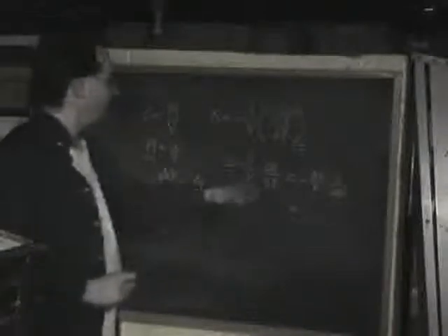So here we can write this as negative delta V over V times 1 over delta P, the pressure. We can use this relationship to replace negative delta V over V with delta rho over rho, times still 1 over delta P. And if we multiply through by delta P and divide through by kappa, we get delta P is going to be equal to 1 over kappa times delta rho over rho.